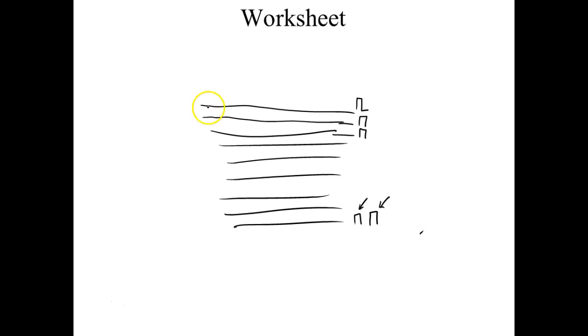So the horizontal would give us a sync every time we got to the end of the line. The vertical would tell my projector over there to reset everything back to the wall, up to the top left. And that's what you're doing when you specify the resolution on your display. Okay. So what we're doing, we're synchronizing this, right? Does that make sense so far?